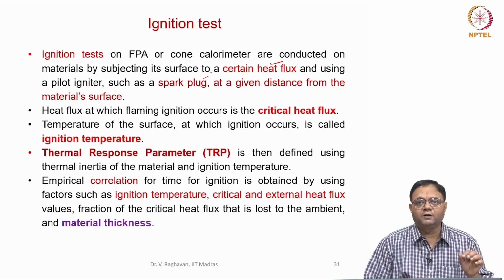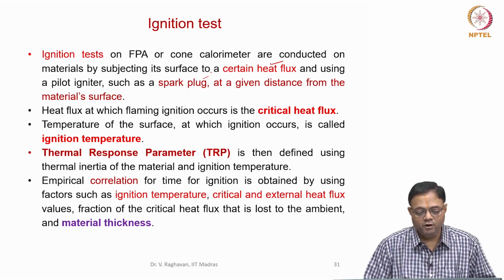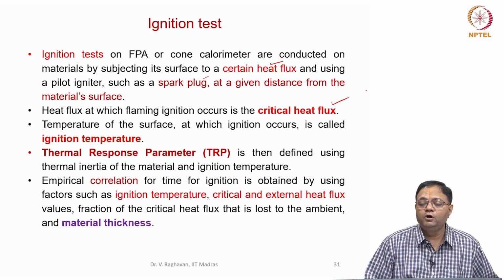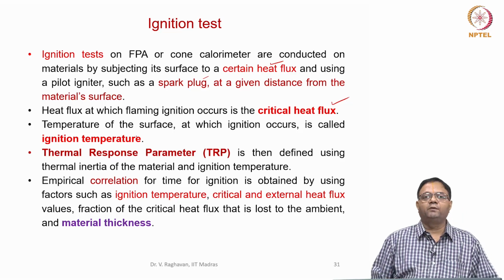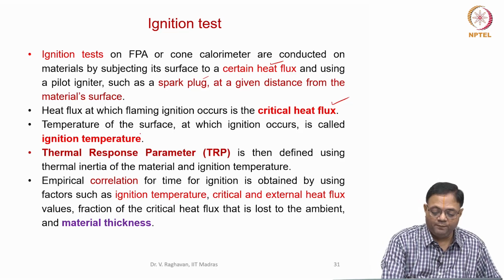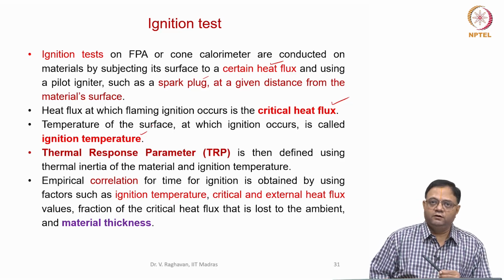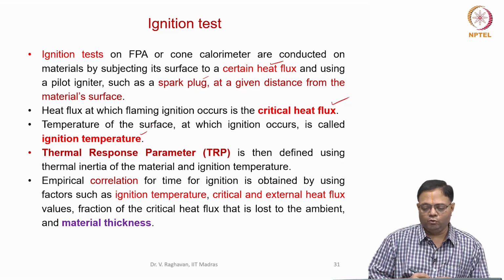We have to keep it at a location where stoichiometric mixing has happened, or at least a flammable mixture is present. This critical heat flux data is tremendously important for us to quantify a material to be used in several applications. Similarly, the surface temperature of the material can be recorded, and the ignition temperature, that is the value of the surface temperature at which ignition has occurred, can also be taken into account.